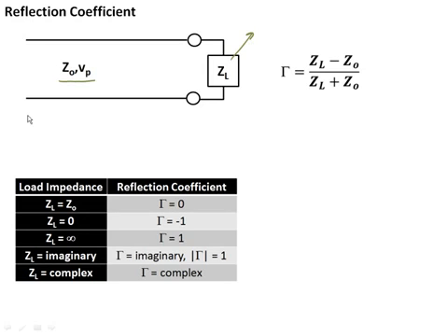But what this diagram represents is a transmission line with some kind of wave propagating down it, feeding energy into the load which you're driving. And that load could be an antenna, it could be some kind of detector, but this is really what we're trying to do with transmission lines: use high frequencies to drive some kinds of loads. In this case we write our reflection coefficient as the load minus the line impedance divided by the load plus the line impedance.